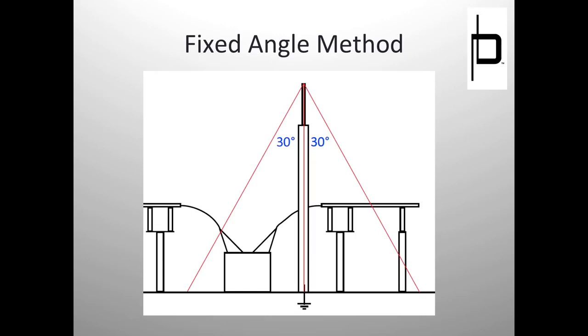So a mast or a shield wire or something that's grounded that if it's struck, it's safe. In other words, not your equipment, right? Your expensive equipment, your bus, your breakers, those are things you don't want to get struck, right? So those things, that's what we want to shield from. So to do that, with passive shielding electrodes, we put up shielding masts and shielding wires. Those are things that can safely get struck and divert that energy to ground, so that your equipment doesn't get struck. Right, so that's what we have here.